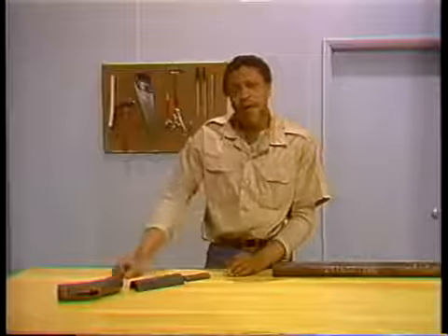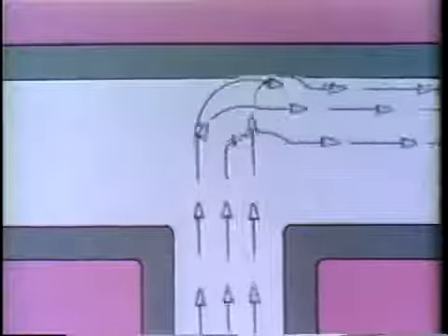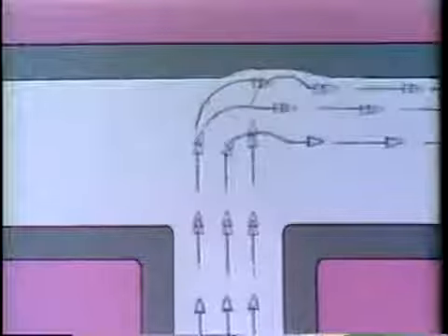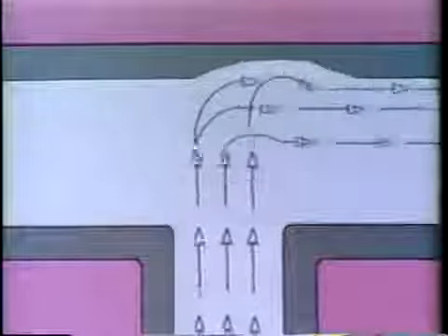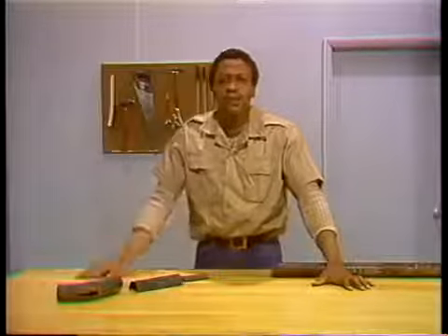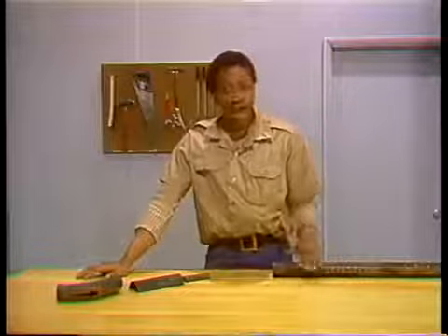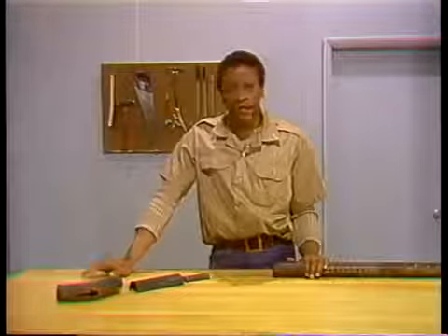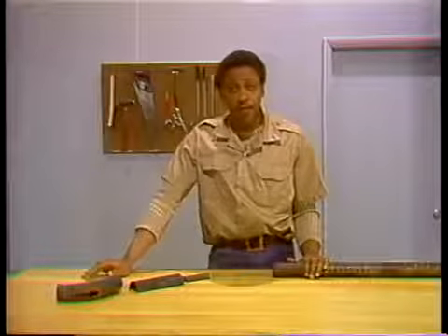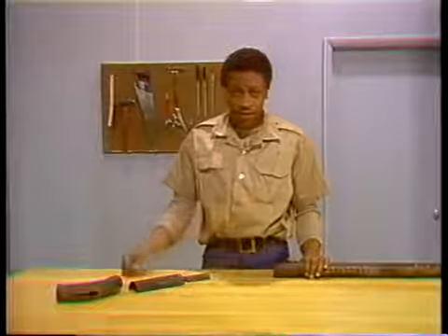The next basic cause of tube failure is erosion. Erosion is the gradual wearing away of tube metal. This weakens the tube. It can occur on either the inside or the outside of the tube. Erosion on the inside is produced by the flow of water or steam, on the outside by the flow of gas and ash. Erosion from gas and ash can be particularly severe in coal-fired boilers because they produce large amounts of ash, which is very abrasive.